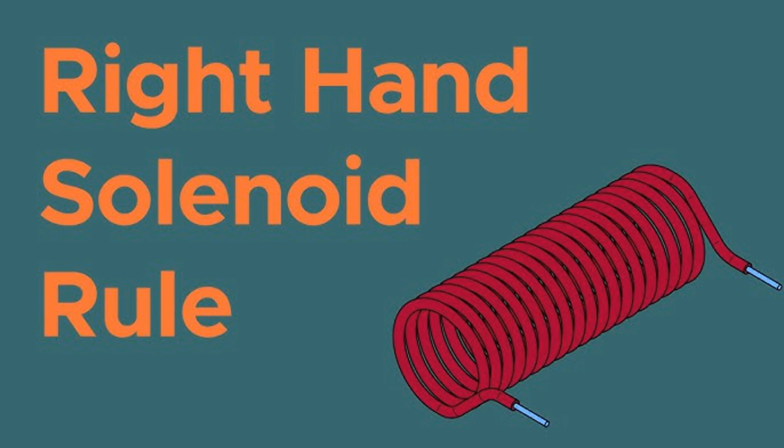8. Open frame solenoids. Description: these solenoids have an open or exposed frame, which allows for easy installation and cooling, but at the cost of reduced magnetic efficiency. Operation: the core moves freely within an exposed frame, and they are often smaller than tubular solenoids. Applications: suitable for light-duty applications where cost is a priority, such as home appliances, office machines, e.g., printers, coin dispensers.